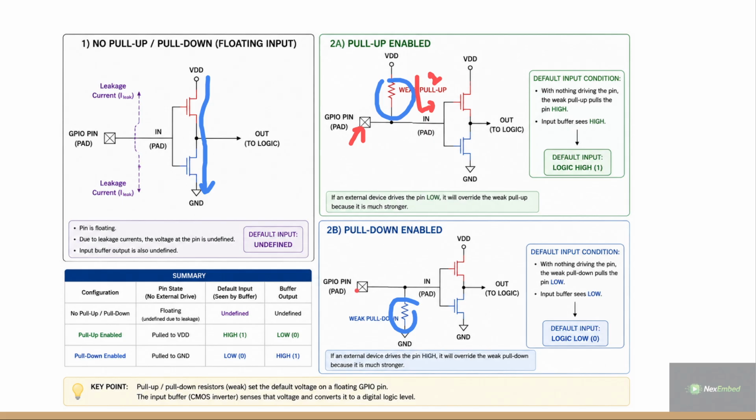In this case, if the particular pin is not connected, it by default gives the value as 0. So what happens if it is 1? It will have the inverter and change to 0, and my PMOS will be 1. During default time it gives 1 as the value. Here it by default gives 0 as the value.